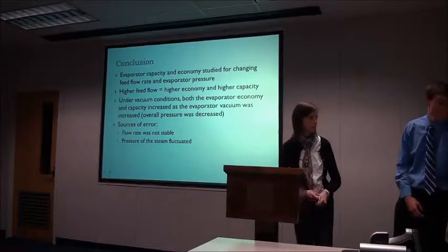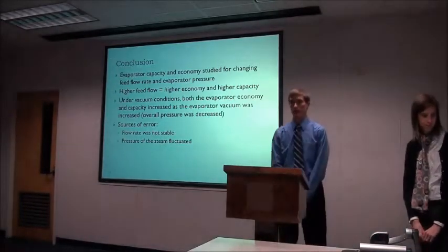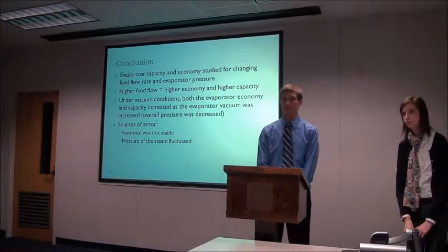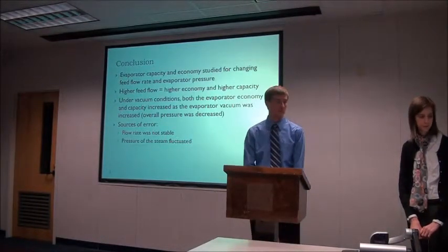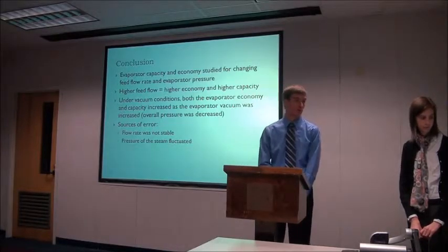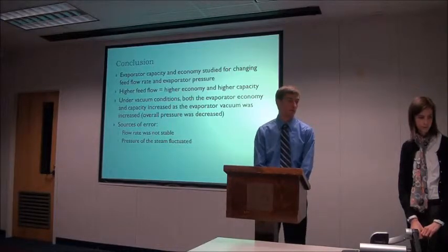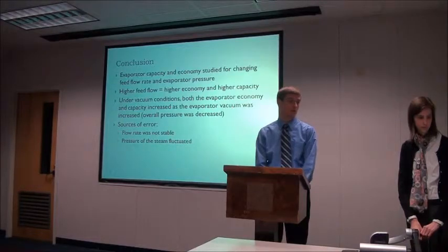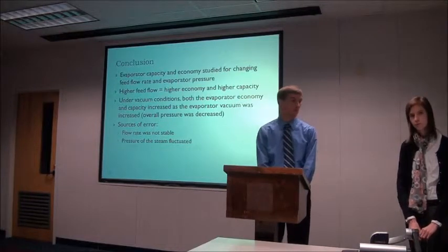Now Scott will cover the conclusion. We found that our trends followed what we expected in our theory. A higher feed flow rate equals a higher economy and a higher capacity, whereas under vacuum conditions, both the evaporator economy and the capacity increase as the evaporator vacuum was increased, so the overall pressure was decreased in the end.